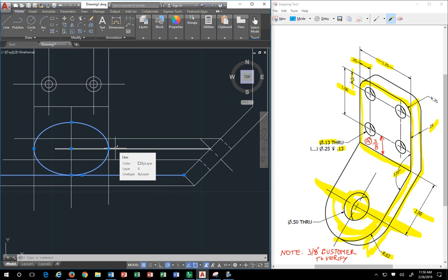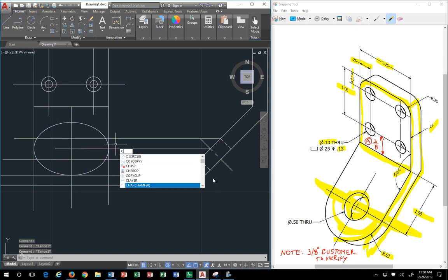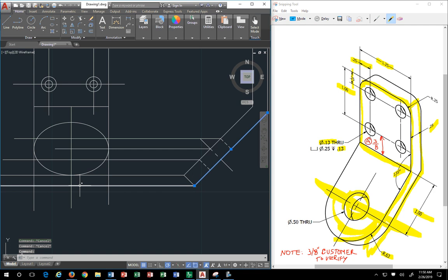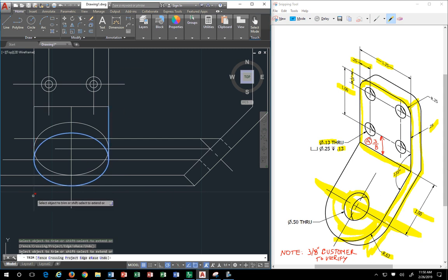Okay? To make the back side that you see here, see this back side, how you see a piece of it there? All you have to do is copy. Just copy this from here to here. That's it. Just copy it straight down. Because this represents the front and this line represents the back. Then you can trim. Okay? And the trim is based on where the perimeter lines are, the perimeter of your object. So I'm going to trim the back first so you can see the back side form. Okay? And then the front.